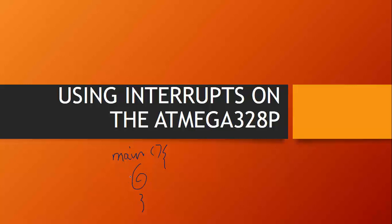And if you have an interrupt that is enabled, the CPU never has to monitor any of the interrupt triggers that you are working with. The CPU can just do what it wants. There's other circuitry that monitors the interrupt, and should an interrupt occur, it branches out, services the interrupt, and when the interrupt is done, it comes back to the exact place where it left off, and the CPU can continue executing the code.